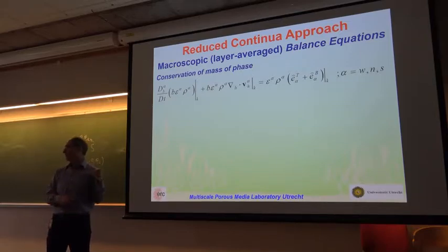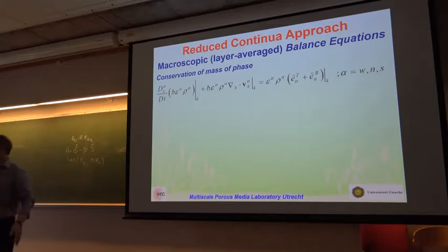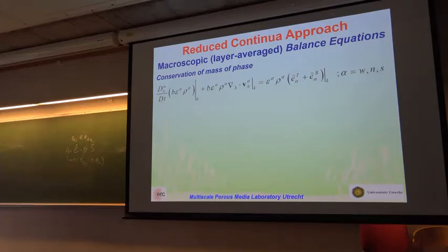Yeah. But I think B must be out there explicitly, because B can be constant in time or space even if rho is not constant, which is compressible, and the other way around. Rho can be constant and B variable in time and space. So if I make a choice, I would put B explicitly out there instead of burying it in rho. Yeah. So what is the thickness of the layer between water and water vapor? The layer thickness is dependent on what material is in there. Water, say argon and argon vapor, right?